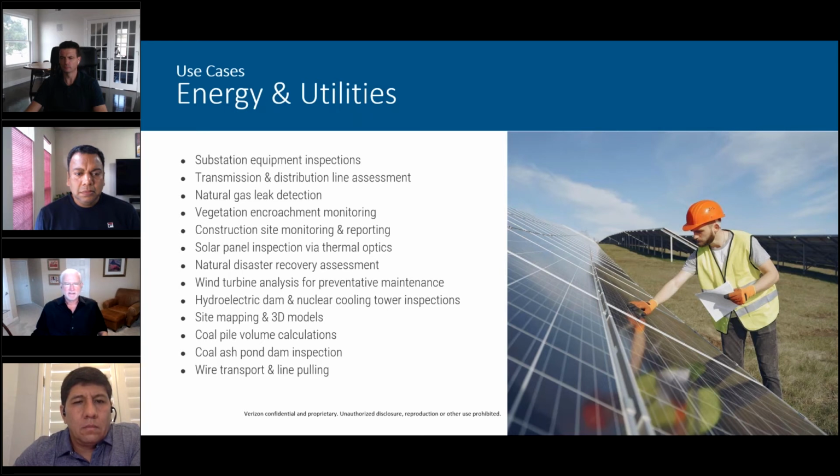Construction management and site monitoring is something that all these companies are using. Besides utilities, construction firms were our biggest vertical up until utilities, which have really taken off lately. But now we're talking about doing site surveys, surveying the grounds beforehand, and then doing progress photos as you go along. And I'll come back to one specific to utilities in a little bit. Solar panel inspection via thermal cameras. It's actually a revolution. Previous to using drones and thermal cameras to detect a bad panel, you actually had to go out in the field, and you've seen how massive some of these arrays are. They'd have to unhook the wires and actually measure each panel individually to locate the problem.